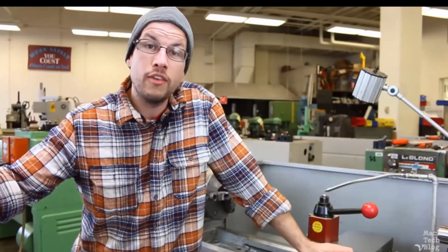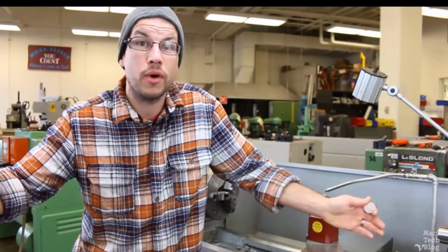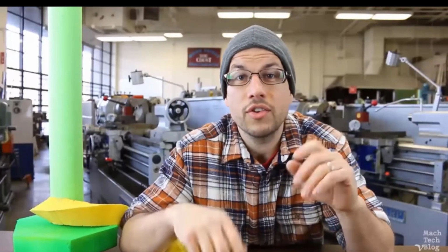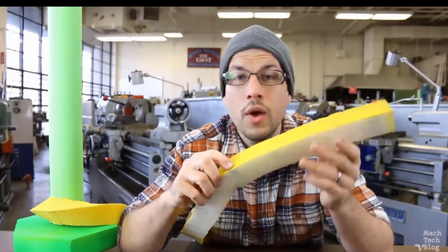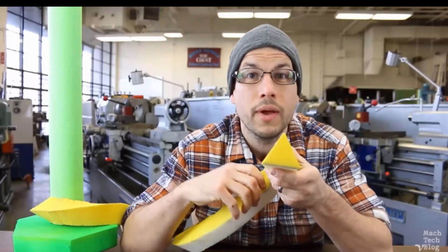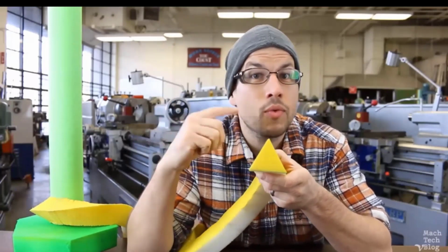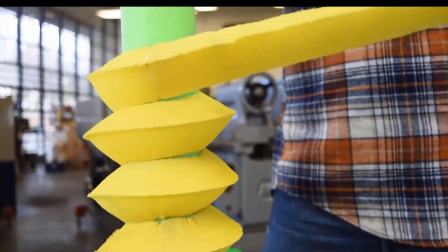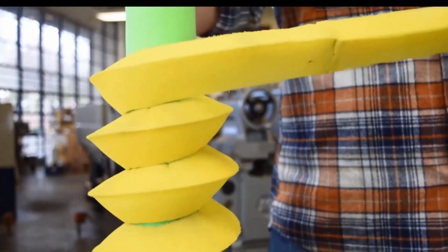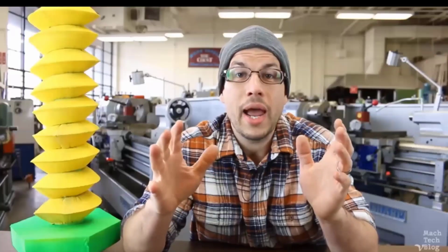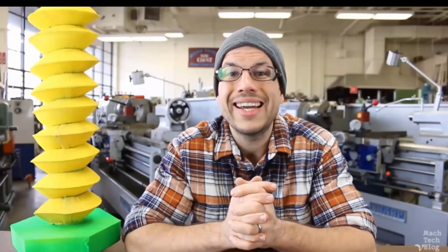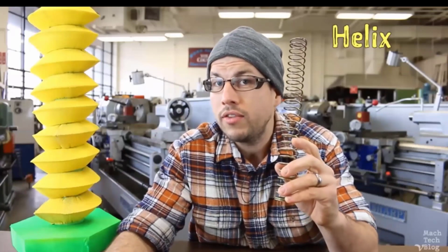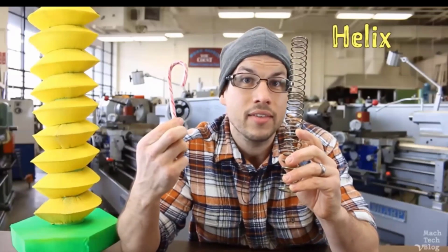So as a technician, or a mechanic, or a machinist, you'll definitely need to know a little bit about them. Essentially, a screw thread is a long wedge with a profile of some two-dimensional geometric shape, like a triangle, that's been wrapped tightly around a cylinder, or in the case of tapered threads, a cone, with each wrap of the wedge snug against the previous wrap. This path, which the wedge follows, is called a helix, and it can be found in many other common objects, like coil springs, or, around this time of year, candy canes.